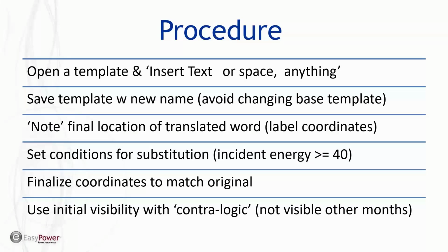Now, just real briefly, I like to follow a procedure that allows me to, for one, not contaminate templates that are built into the tool. It lets me start with a fresh template anytime I want to make changes. But the basic advice is to save a copy of the template as you modify the contents, and that way you're not contaminating the original. And you can go in and find it if you've named it appropriately. You go in and find it with a text editor and or delete it if all goes wrong.